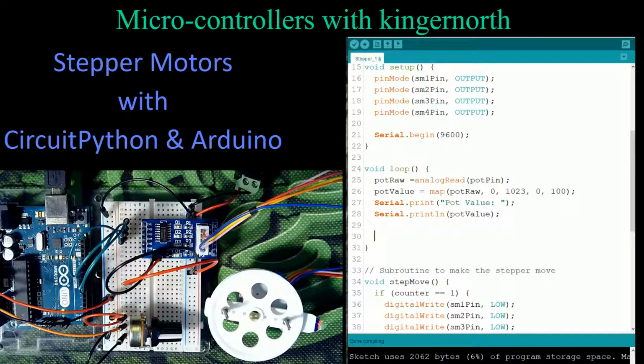So in my main loop, I need to have 3 different conditions that happen. And I'm going to explain this a little bit before I get typing too much. We have a range that we can read from 0 to 100 as the determined value that we can adjust with our pot. And when we approach 0, which is if I take this pot and turn it counterclockwise, all the way down to the left, it's going to be at 0 input. When it's a 0, I want this motor to be turning counterclockwise from the way that I see it. So from 0, it's going to be moving at its fastest rate when it's all the way down to 0.